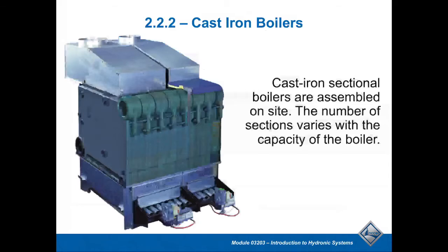All right, so let's take a look at some of our cast iron boilers that would be going on in here. In a lot of the cast iron boilers, they do have pretty good heat transfer characteristics, but one of the problems you run into is you have to be a little bit concerned about running them for an extended period of time with too cool of a return water, where you would have excessive amounts of rusting that goes on in these cast iron sections.